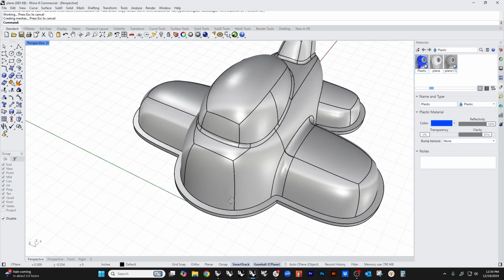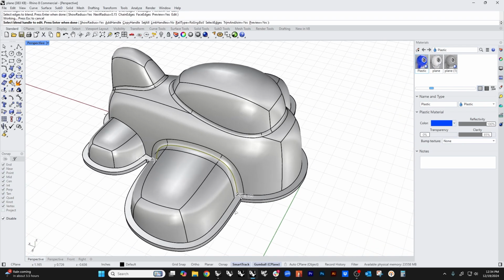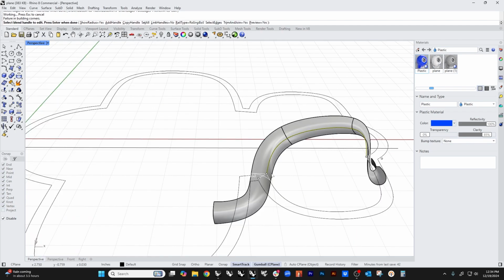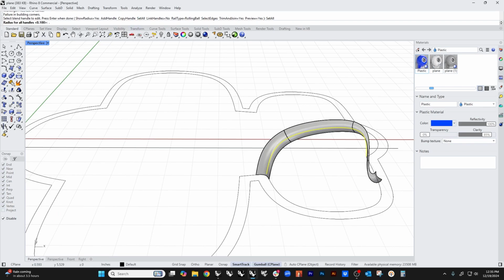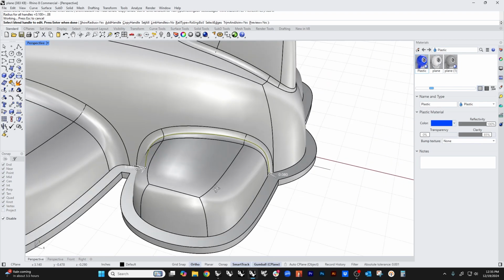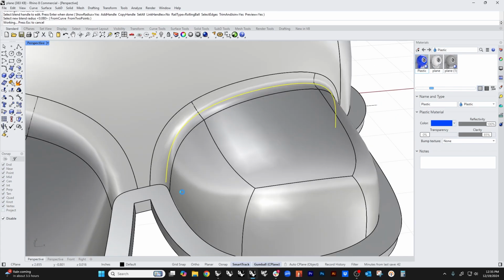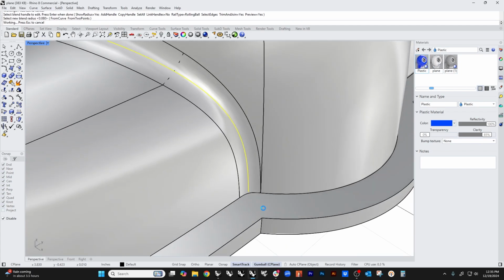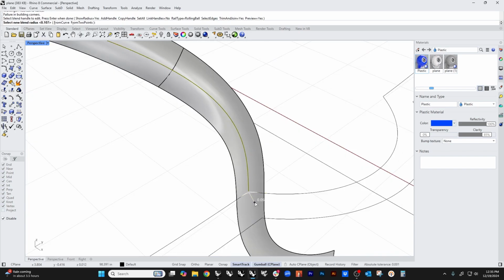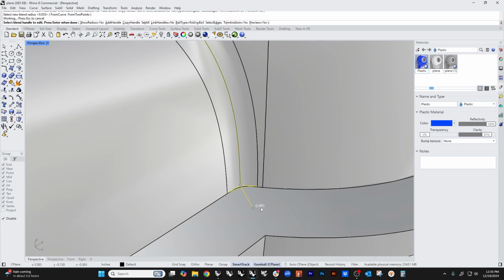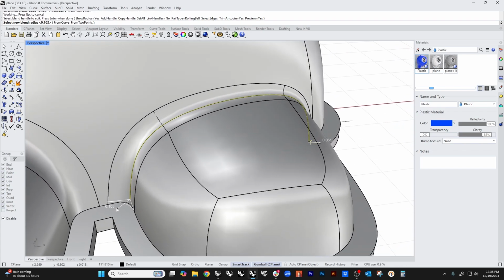And we want to keep track of what we're doing with our fillets, because we need to make sure that we're starting with our big fillets and moving to our small fillets. So that one is too big, so let's do set all 0.1, still too big, set all 0.08, and it's coming down. So 0.08 is now the smallest fillet that we've got, right? And maybe we come up to 0.1 here, and I would love for this to not be so close to that edge. So I'm going to see if I can pull this out a little bit more, and it doesn't like that. So I'm actually going to go the other direction and move it away from that edge. So 0.06 is now the smallest value that we've got.